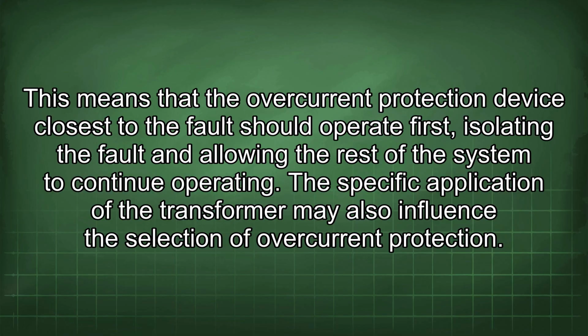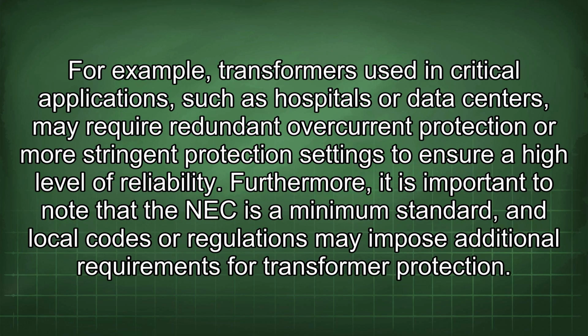The specific application of the transformer may also influence the selection of overcurrent protection. For example, transformers used in critical applications such as hospitals or data centers may require redundant overcurrent protection or more stringent protection settings to ensure a high level of reliability.